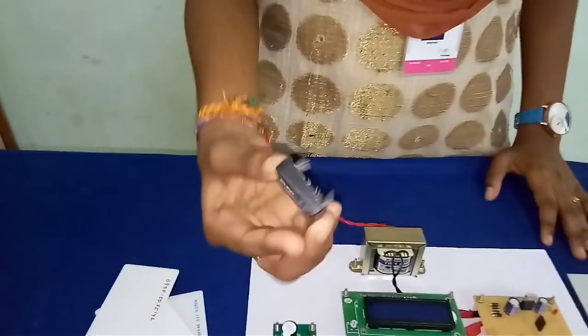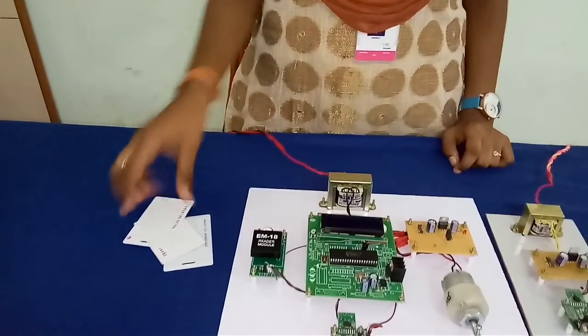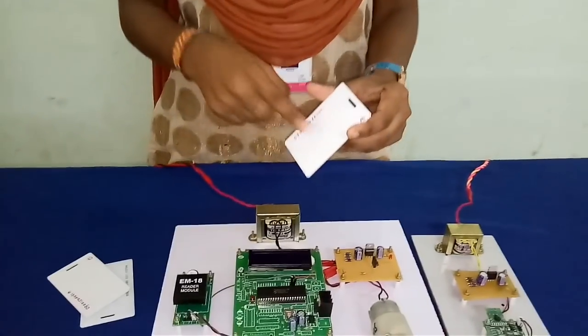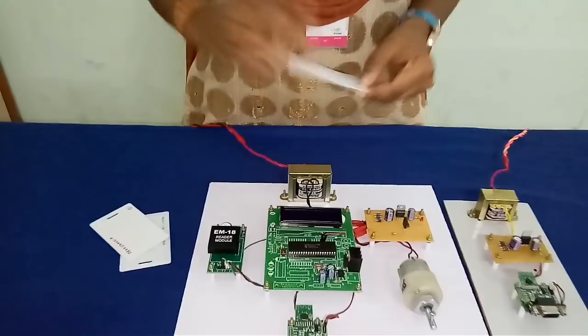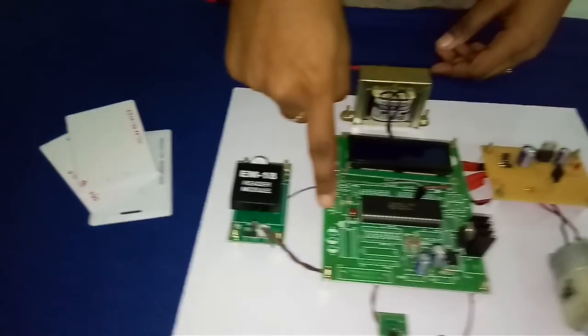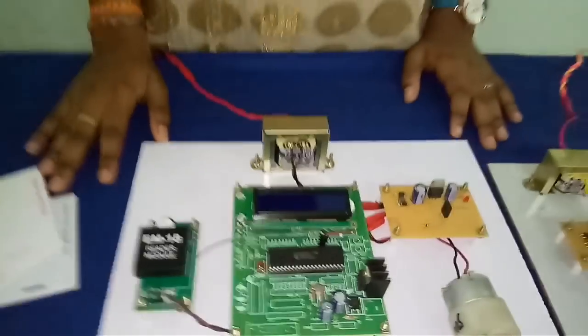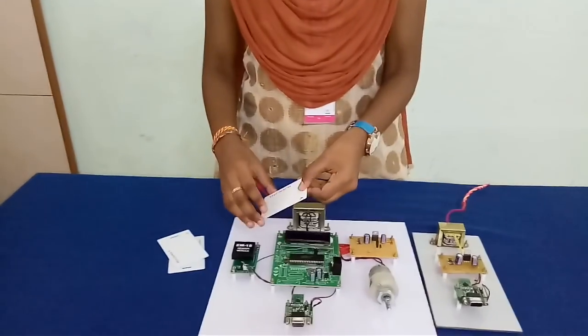This is the RFID reader. The RFID reader is surrounded by windings. The RFID reader is used to gather the information from the RFID tag. Radio waves are used to transfer the data from the RFID tag to the RFID reader. It produces the signal and it passes through the PIC board. In our project, we are using the low frequency range, 134.3 kHz. The distance from the RFID reader to the RFID tag is 1 cm.